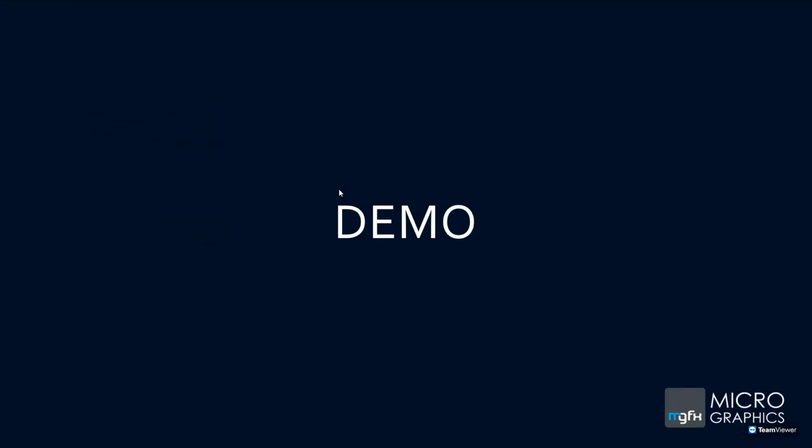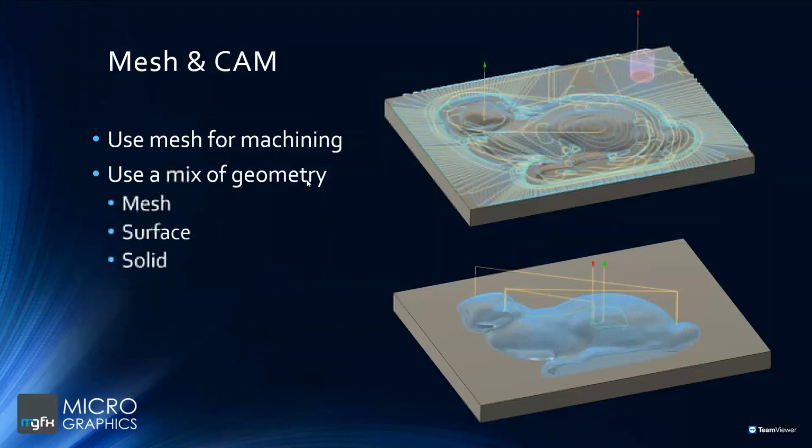Okay, basically covered the demo there, looking at those options. Then we get into what I think is quite interesting. You're able to actually use the mesh in the CAM environment, in the manufacturing environment in Fusion. So, another advantage of Fusion is the ability to import that mesh data into the manufacturing workspace. And so you can use this mesh to create your toolpaths, and there's no need to actually remodel the object at all.